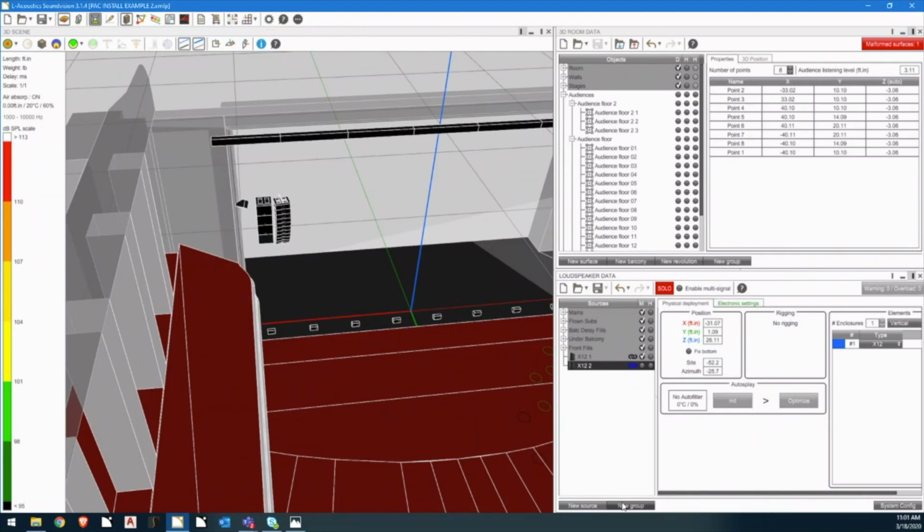And then once I have everything in place, that's when I'll turn everything on in the system. I'll look at all the SPL. I'll balance the SPL across the different systems between front fills and under balconies and mains. I'll find the maximum gain the system can achieve with the gain settings we've set, and I'll make sure everything's timed together.